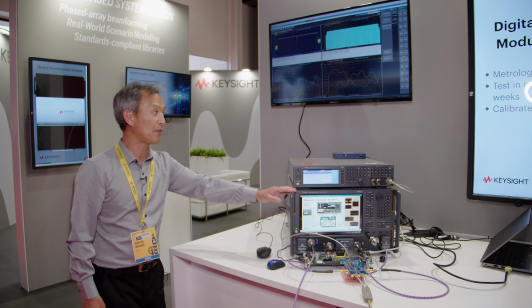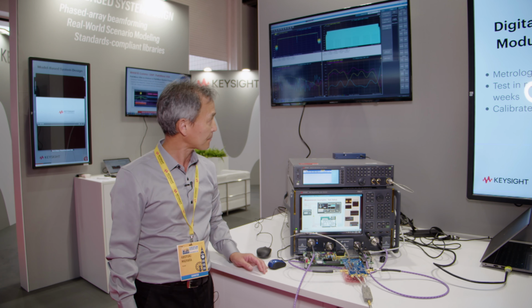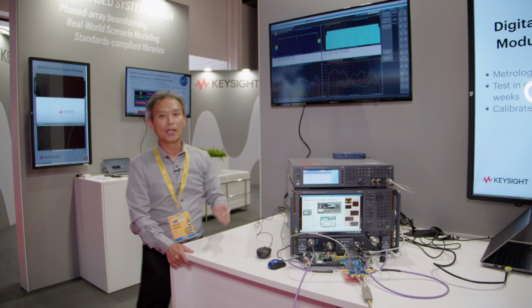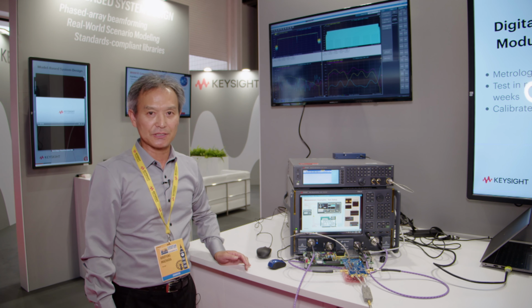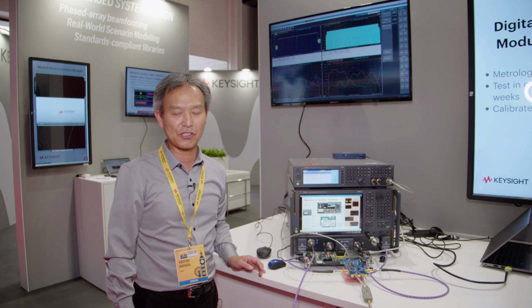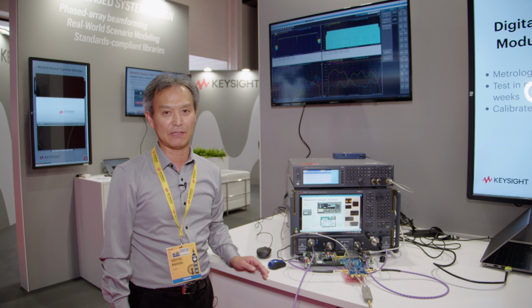A measurement example of the receiver side is shown on the left side. The top windows show the receiver input and the receiver output. The receiver input is an RF signal. The receiver output is the digital signal. We compare those two signals and measure the gain versus frequency, as well as delay deviation and the phase deviation relative to a linear phase response.